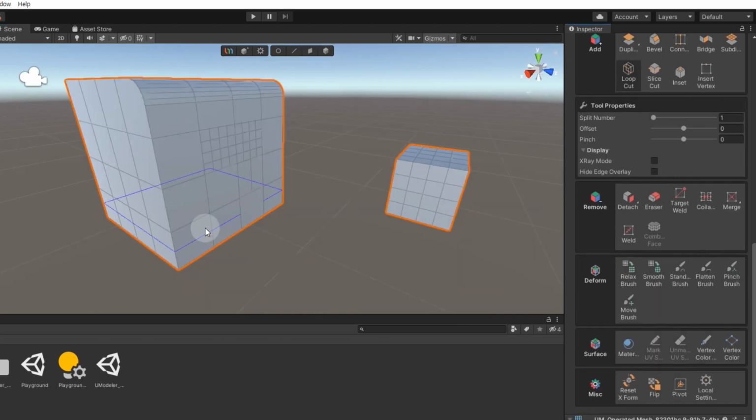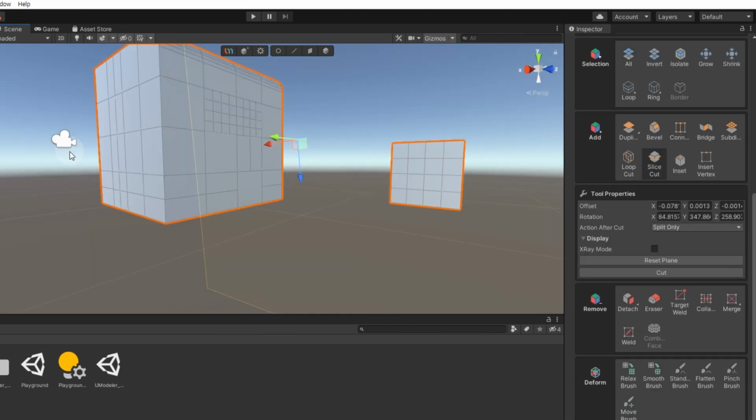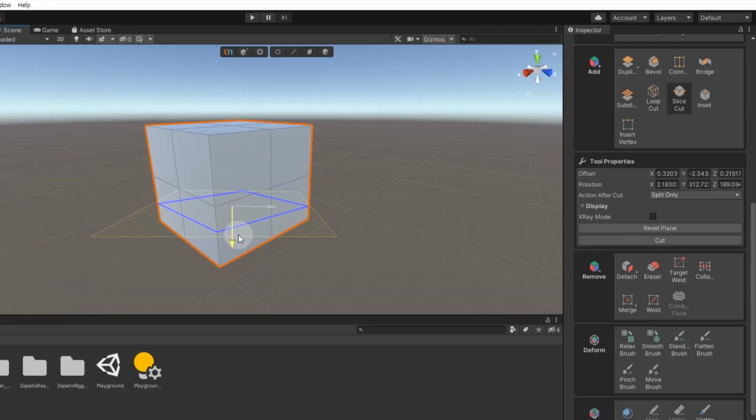Loop cut adds additional edges along the modeling surface for more details. Slice cut creates edges based on a line drawn on the object's surface. You can move or rotate the virtual plane directly, or click both endpoints to draw a virtual line segment to create a virtual plane.